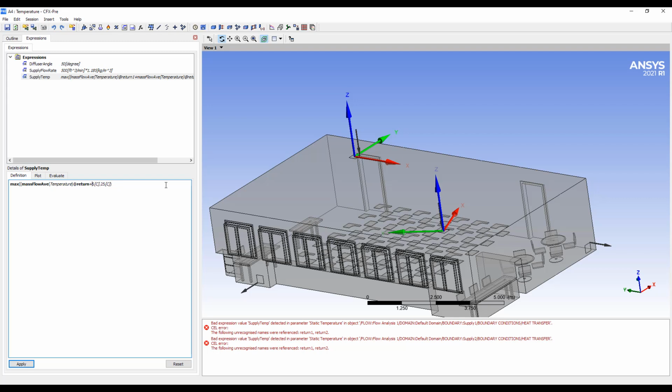And usually it's not 25 C. Usually you want it to be about 20, actually Fahrenheit, be the difference between your supply and return temperature. Now in that case, this expression could cause thermal runaway. If I always have the temperature coming out here much hotter than the return temperature, it's possible that the temperature will just keep increasing and increasing.